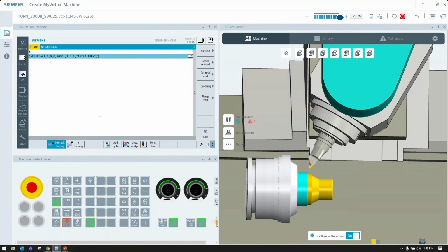So why would this be beneficial? On a lathe, a couple things come to mind. One of them might be that you're trying to do an O-ring groove turn that you don't want to have to spin, or you have an O-ring groove on a 45 that has a really big callout that you can't turn. So this way you could totally do it with interpolation turning.